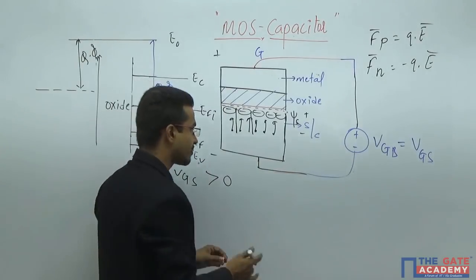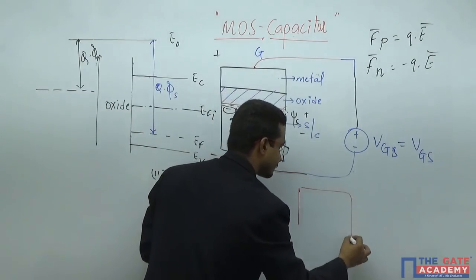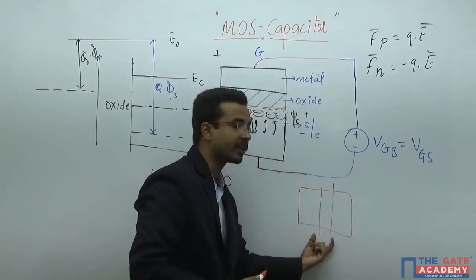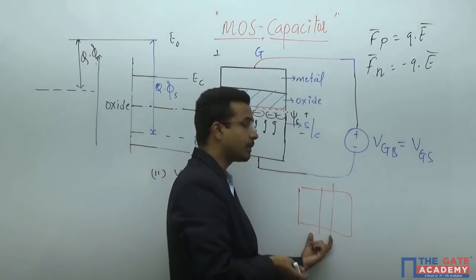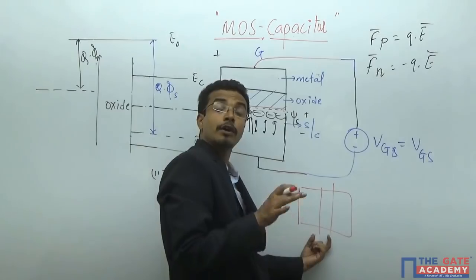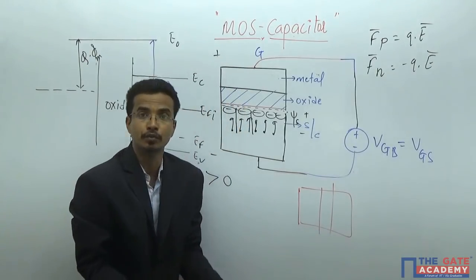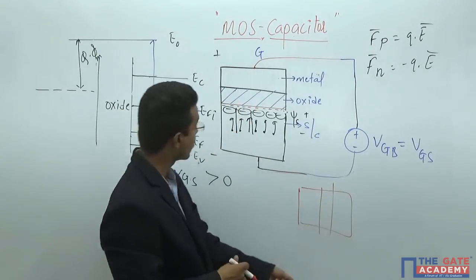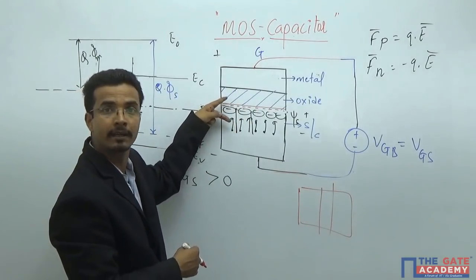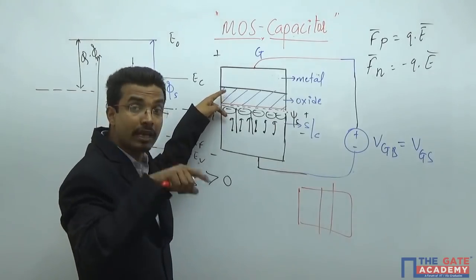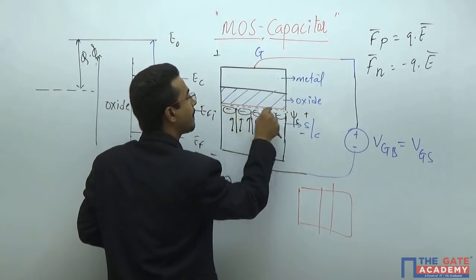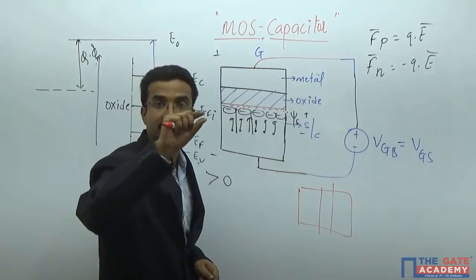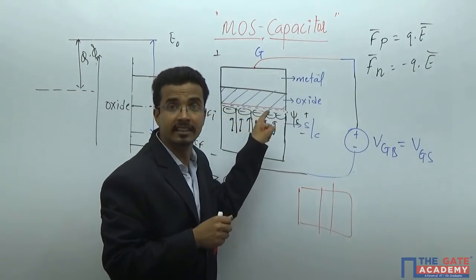That is why you have studied that in the p-n junction, at the depletion region, you are storing positive and negative charges, which are immobile charges that cannot move. That is why you are getting the capacitance in the depletion region. The same type of thing will happen here, but additional to that, you have trapped these charges near the interface, and these are the mobile charge carriers.